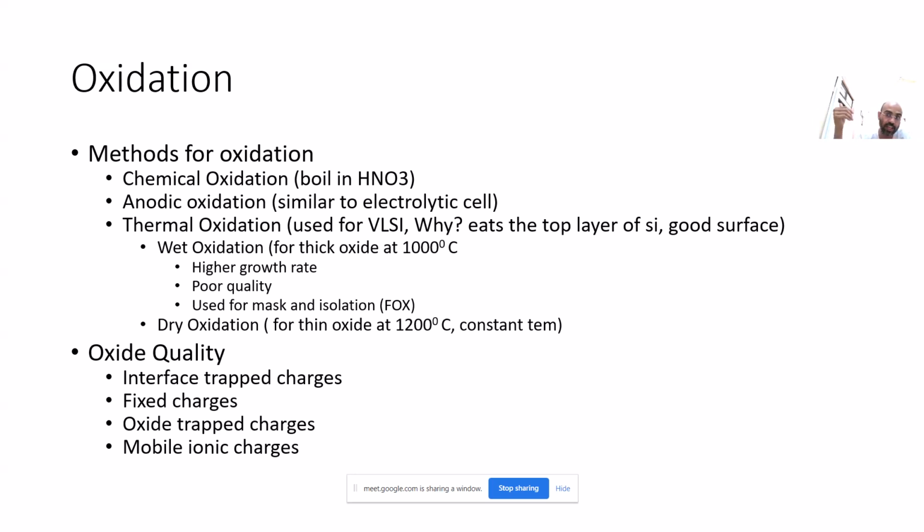So later on, when you etch it out, with whatever method you are using, that particular surface, the top layer, will be removed. That top layer removal is actually good for the silicon for our electronic purpose. Why? Because when we started, most of the impurities, defects, the dangling bonds and all those things were present on the surface.